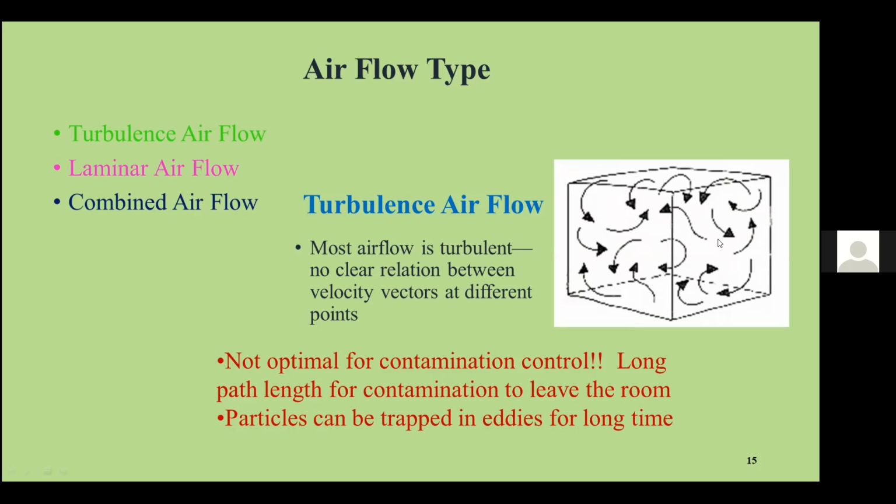If we use turbulent airflow in the clean room, we cannot remove the particle contamination easily, because turbulent airflow traps the contaminated particles in itself. So turbulent airflow takes more time to make a clean room environment. This type of turbulent airflow is available in class 1 lakh type clean rooms.